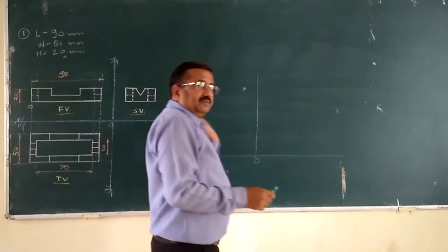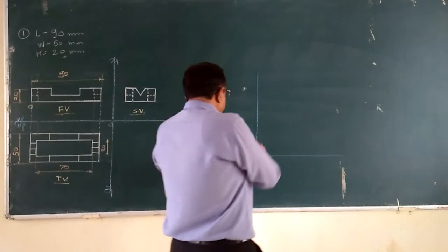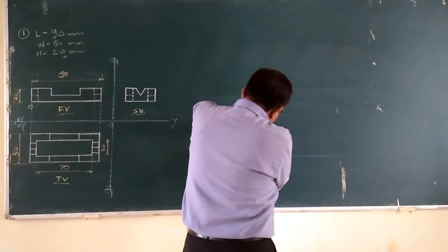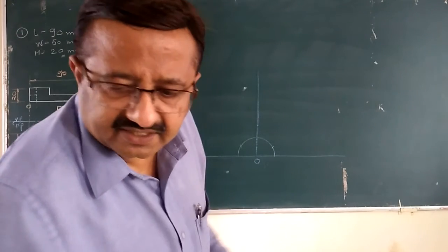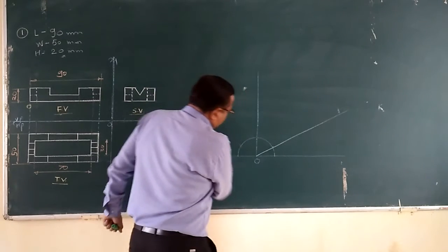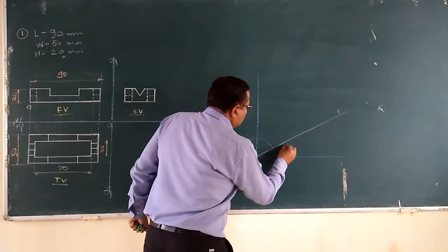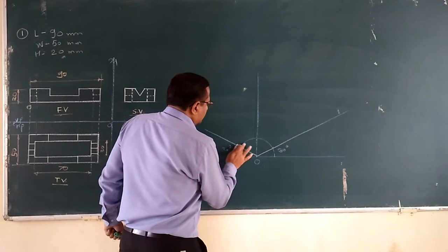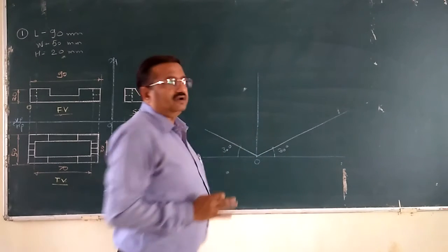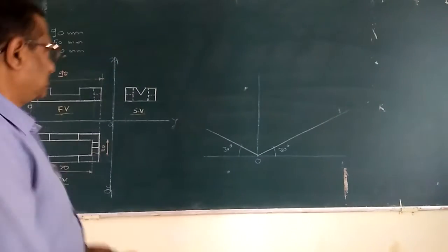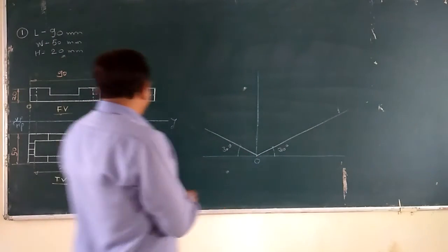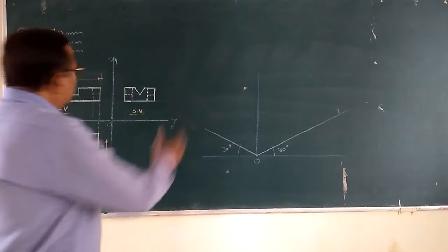As you get left 30 and right 30 lines with the help of a protractor, geometrically I will construct the same 30 degree right and left angular lines here. Right 30 degree line and left 30 degree line. So this is the basic infrastructure required for constructing isometric projections: the vertical line, left 30 line and right 30 line. Now we can proceed with these three lines.